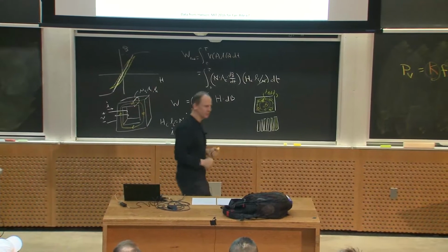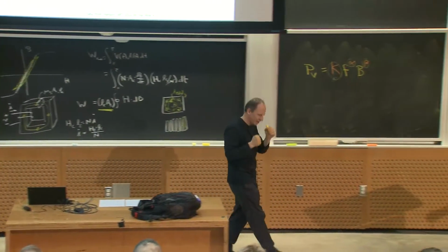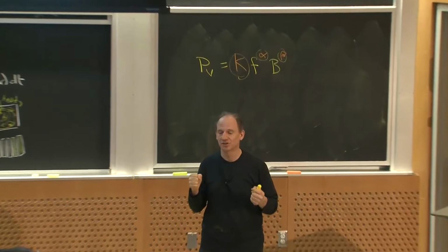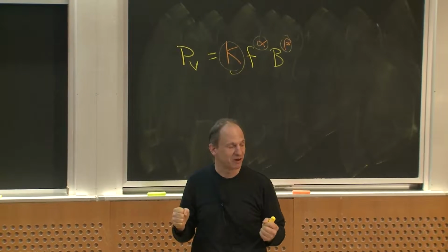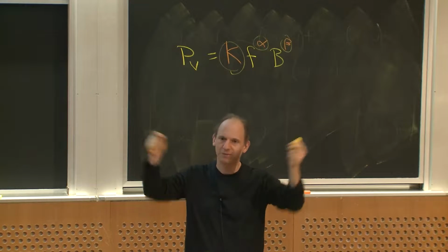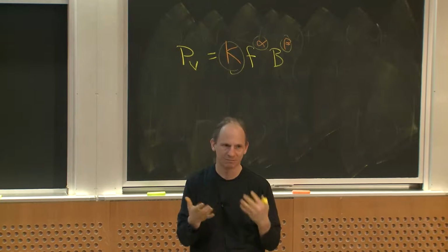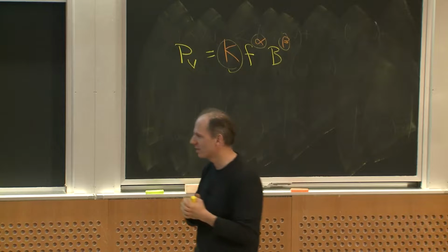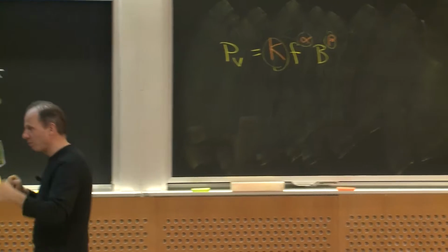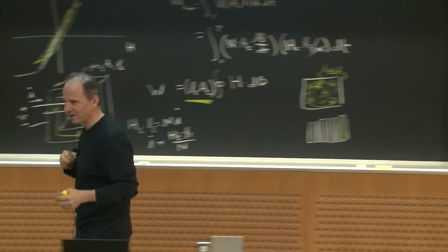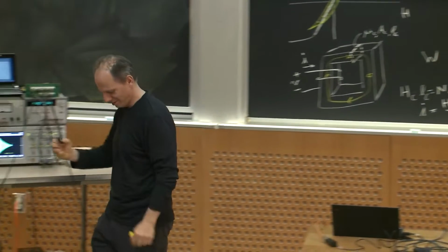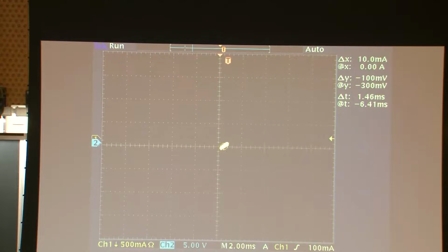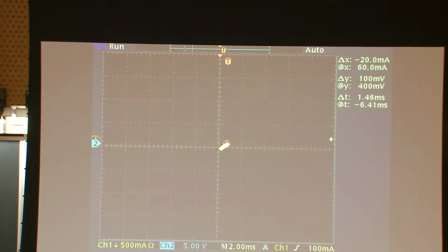Unlike winding loss, where you can write lots of equations and predict it very beautifully, core loss is very much determined by measurement. It's very hard to link the microscopic behavior to the macroscopic behavior, except in limited circumstances. Now, I'm almost out of time here, but what we wanted to show you, and maybe I will hand this over to Mansi. So we have an inductor here, and I'm plotting the current through the inductor, which is proportional to H,